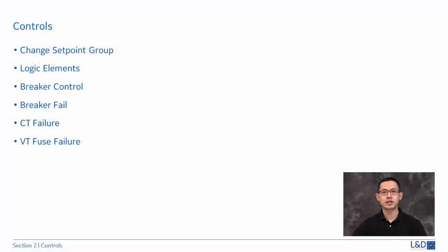In the control section, we are going to introduce these functions: change setpoint group, logic elements, breaker control, breaker fail, CT failure, VT fuse failure. Virtual input command is also under the control. We already introduced it when talking about the virtual input setups.